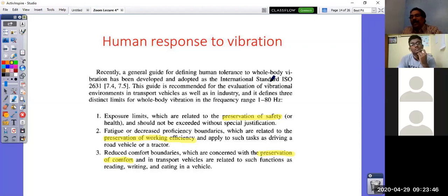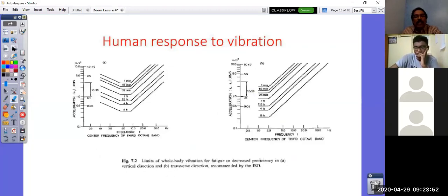For example, you will excite 1 hertz for some time, and how long the excitation table runs is the exposure time. If it is for 1 minute, you take your average value for that particular frequency and mark it. Then for the next, you increase the frequency and again record it. Like that, if you mark, you will be able to plot such graphs.